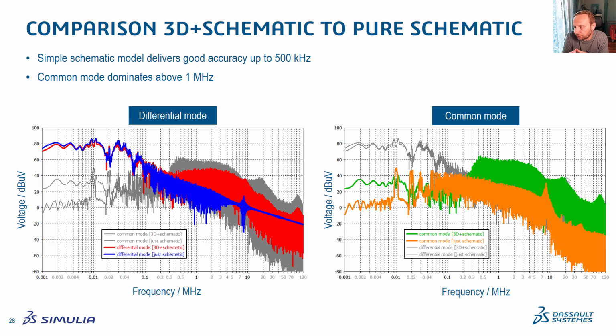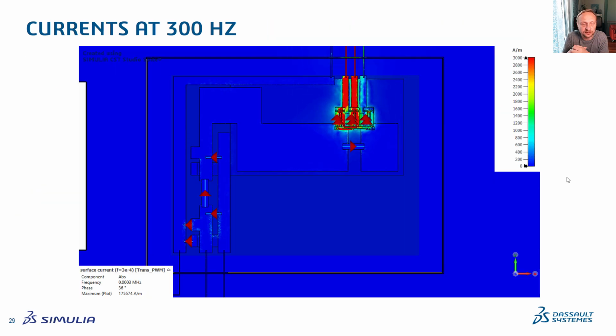When you do this coupled model together with S parameters, you have a much wider frequency range in which your model is valid compared to a simple RLC model. And then additionally to this wider frequency range, of course, there is this visualization. As I have mentioned, we can now take the results from the circuit and feed them back into the 3D solver. And that's what I did here.